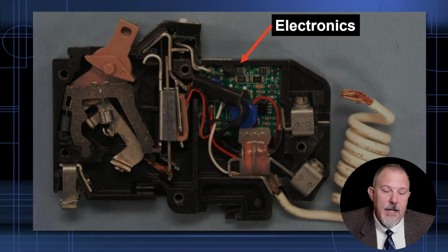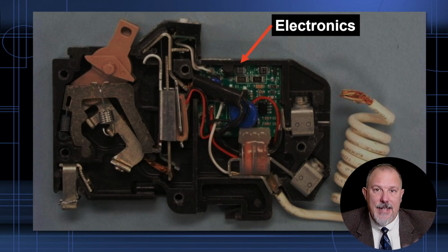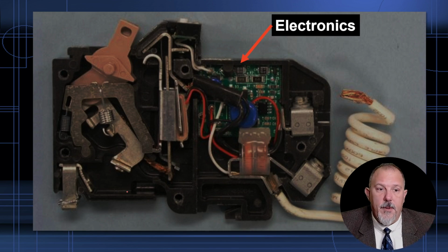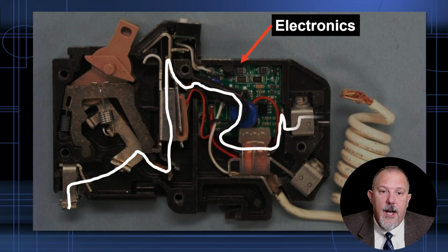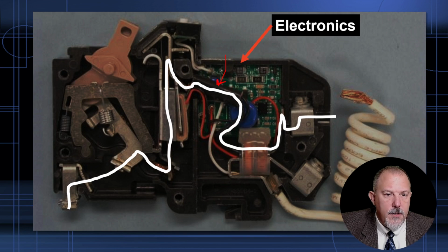All right. Now we're going to follow that same circuit through the circuit breaker from the beginning, from the bus. From the bus, it goes through the contact, up through the bimetal, and this right here is a wire. Over here, right in here, is a braided conductor.